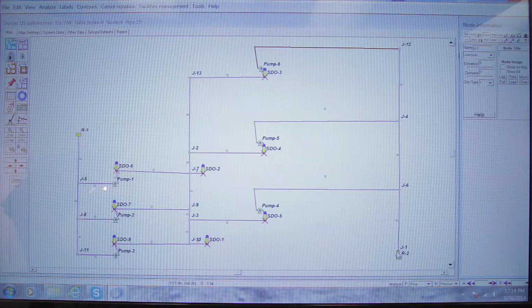And then from that node, we can simulate out and look at what would happen as we're building up the pressure in the shale and it breaking away. We can simulate that as a valve opening up and looking at the cause and effect of how the pump is then going to shoot off the curve because we don't have that head, and we can look at that wave oscillating back. In our reuse water class, we're going to address that and what happens when you have this sudden burst of energy as we break apart the shale.